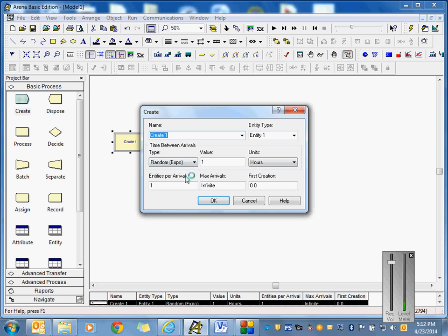is we'll call this, I'm just going to call it Part 1 arrivals. So Part 1 arrivals with an expression, minutes, and TRIA 5, 10, 15. So hopefully you guys got that. So first thing is CNC 1 is putting out parts to our conveyor belts at an expression of 5, 10, 15 triangular distribution in minutes.